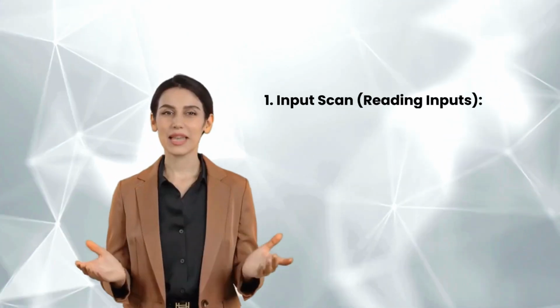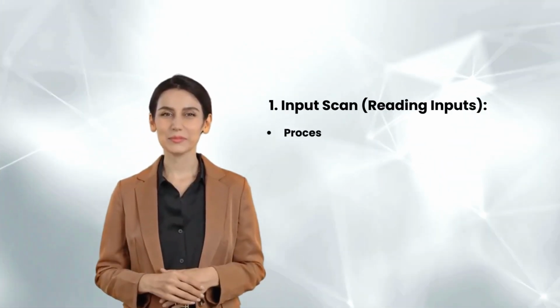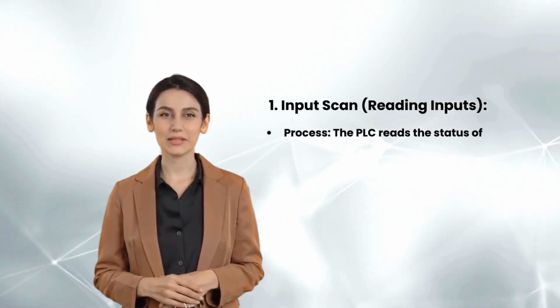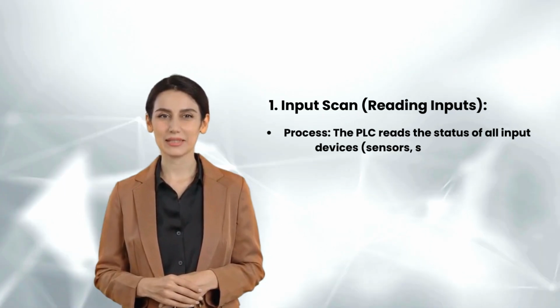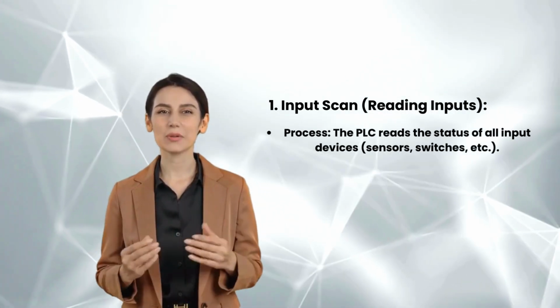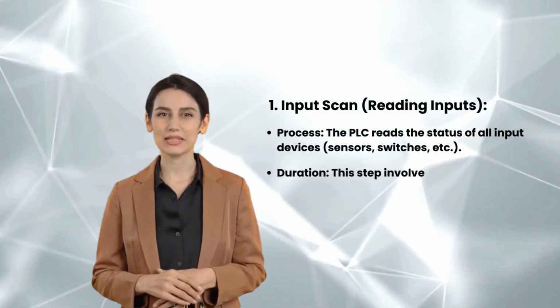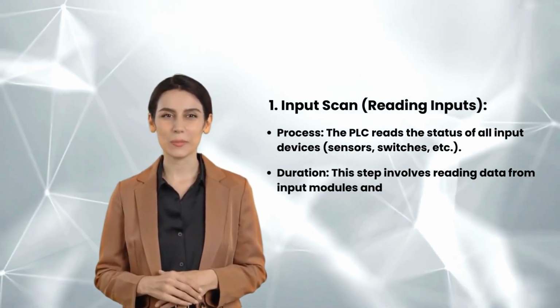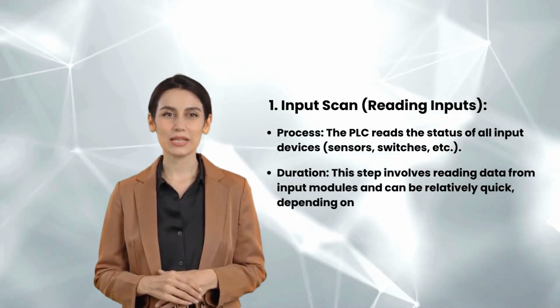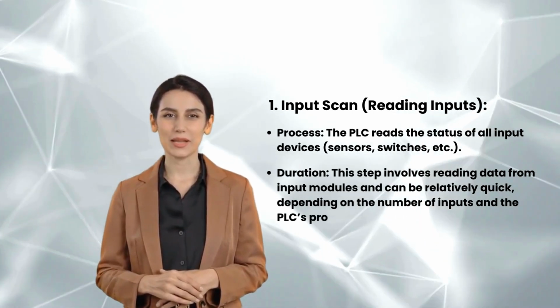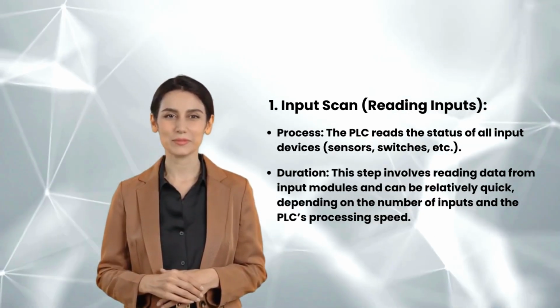1. Input scan, reading inputs. Process. The PLC reads the status of all input devices, sensors, switches, etc. Duration. This step involves reading data from input modules and can be relatively quick, depending on the number of inputs and the PLC's processing speed.